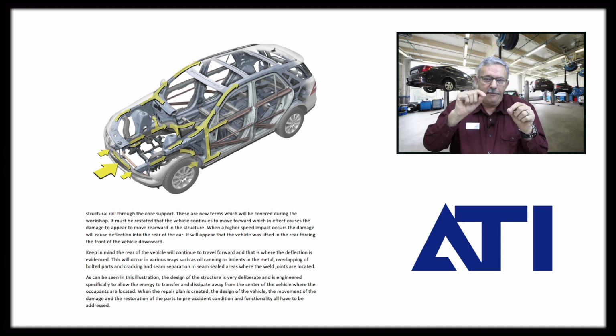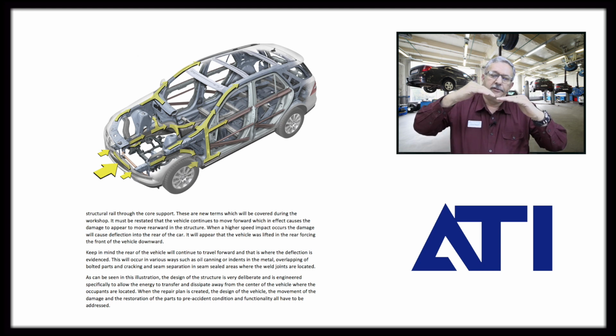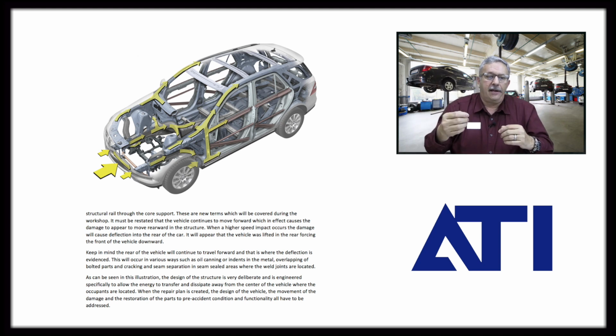As that occurs, remember the damage is going to dissipate. Things that I have to look for on a substantial impact: did it crack the windshield? If it cracked the windshield, that means that the roof section, as the damage was coming back and moving forward, there was enough stress put into that windshield that it cracks it. Very common occurrence.